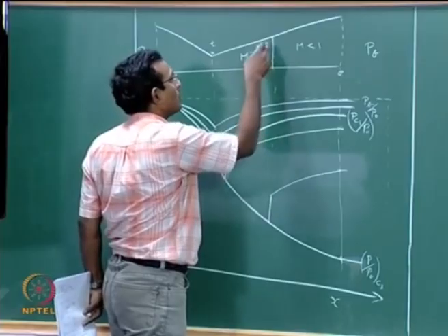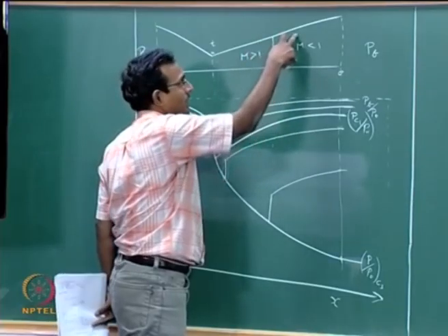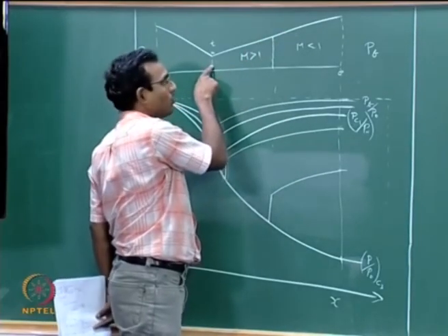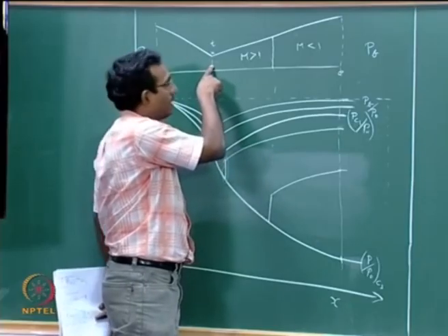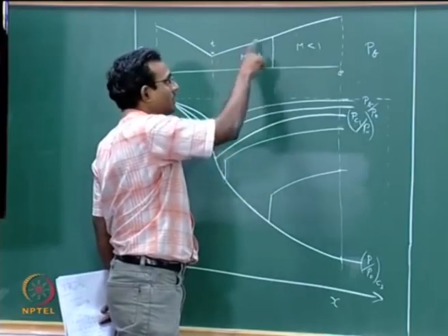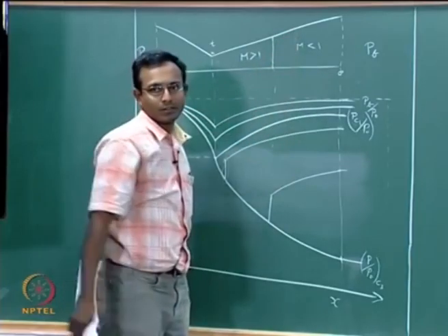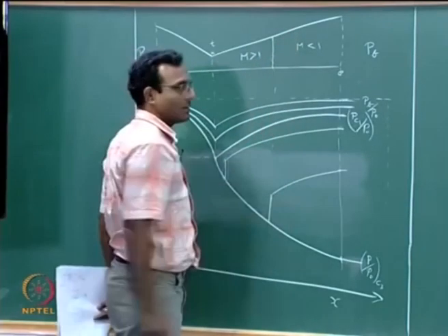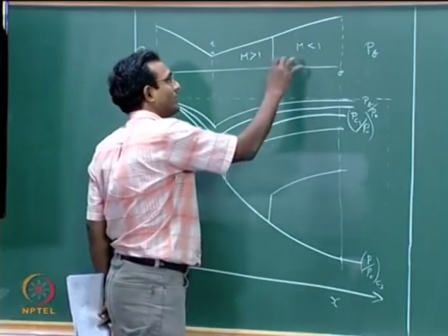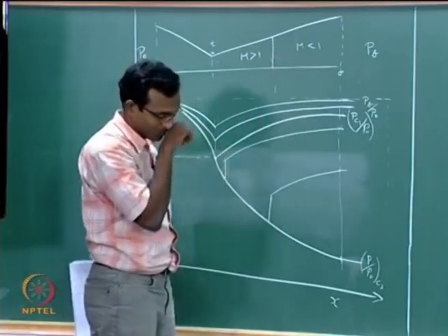If the shock goes more out, the shock sits at a higher area. From throat M equal to 1, I have become supersonic and it is a diverging duct, so it is going to increase in Mach number much further, go to a higher Mach number here, and so the pressure jump will be higher, not a drop. It is actually an increase in pressure across the shock.